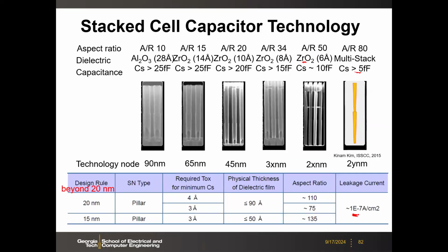I just want to give you a sense of what kind of capacitance value it is, and what kind of geometry factor, like this AR ratio. Those are the key features you need to understand for today's DRAM cap. Bit-line capacitance should be on the same order, like femtofarad.